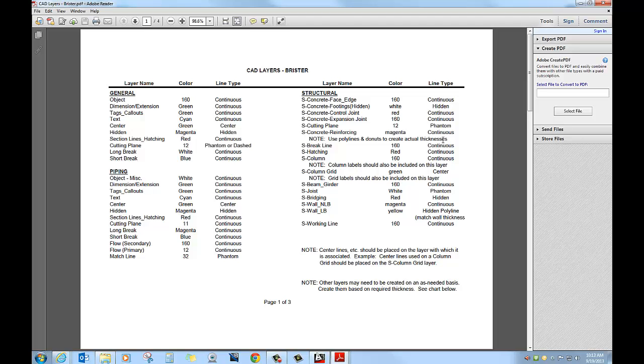So when I draw that particular rebar, if it's labeled as such, which it will be, then we need to use a donut, make the center diameter 0, make the outside diameter 1/2 inch. That way it's the actual diameter of that rebar. Same way with the polyline.